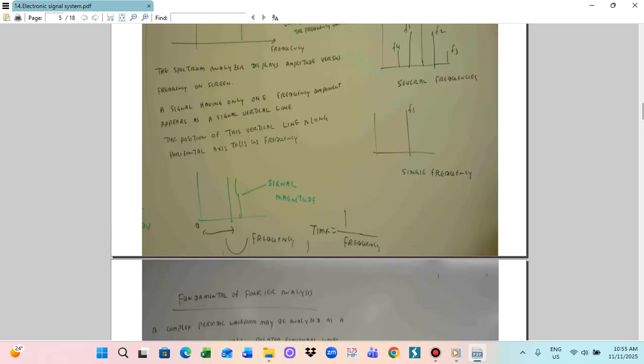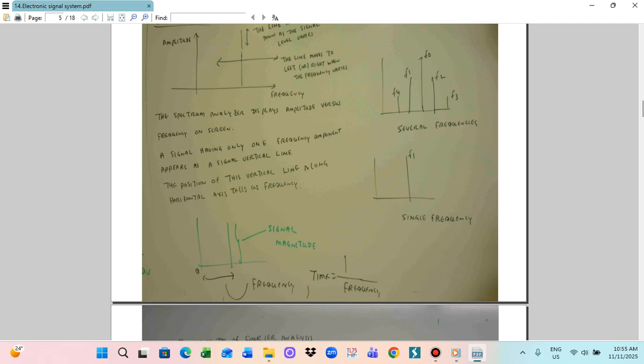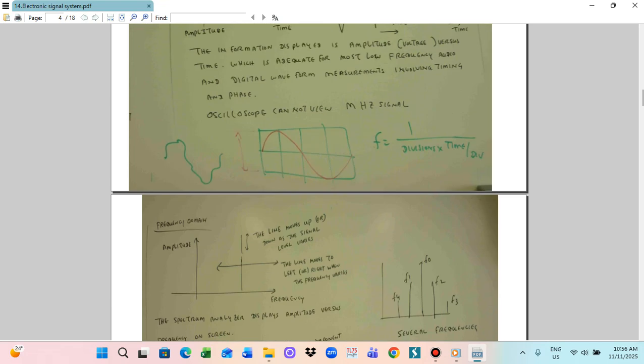So this is a scope. When you see the waveform like this, how do you calculate the frequency? Normally, the amplitude you can calculate here, from this one to this one. This is the number of divisions, and the number of both are the divisions, so you can calculate the amplitude. And then this waveform has a start point and an end point for one complete waveform.